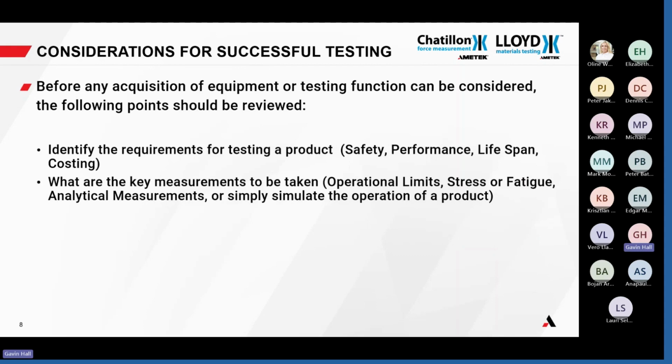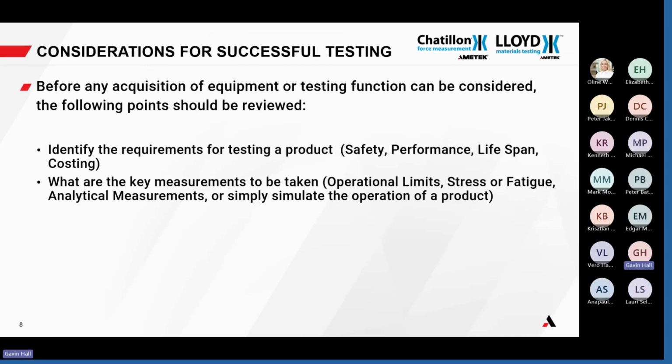So is it operational limits? Is it stress or fatigue? Are we looking at pushing that product to its design limits? Analytical measurements, so during its time, key measurements can be taken. Stress or strain, or operations of the product can be simulated using the equipment. Simply simulate the operation of the product. So is it fit for purpose as it's going into an end user?